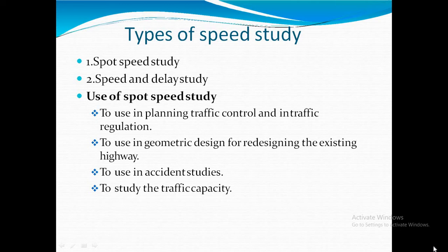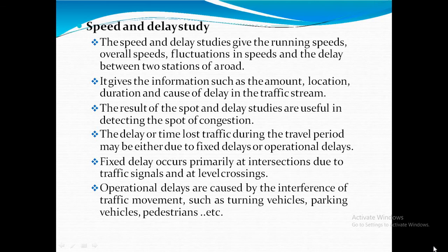and to use in geometric design for redesigning the existing highways, for deciding design, and to use in accident studies, and to use in traffic capacity to decide the speed trends, to compare diverse types of drivers and vehicles under the specific condition. So these are the uses of a spot speed study.